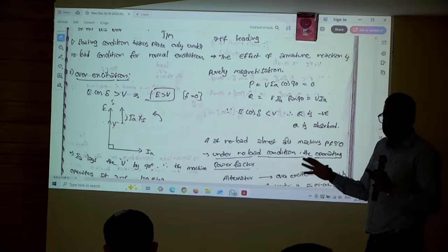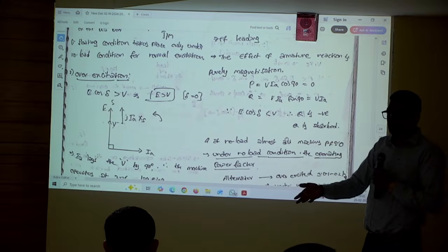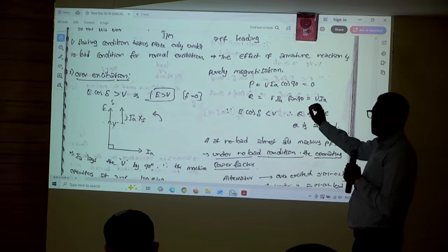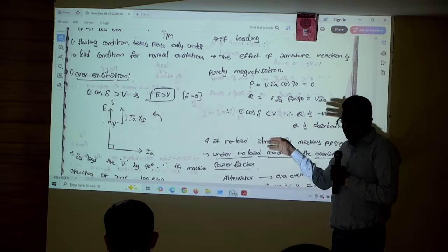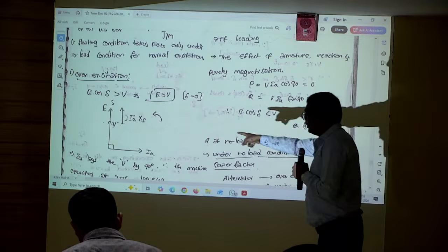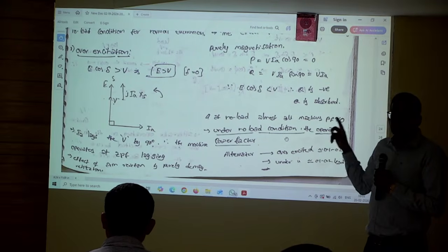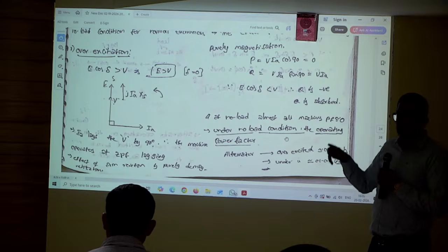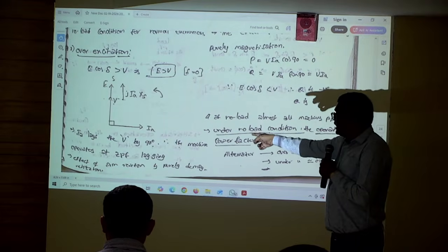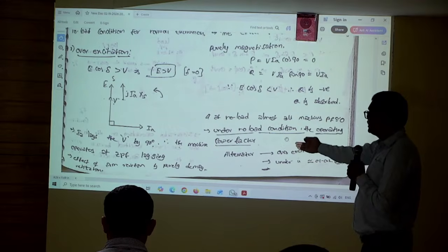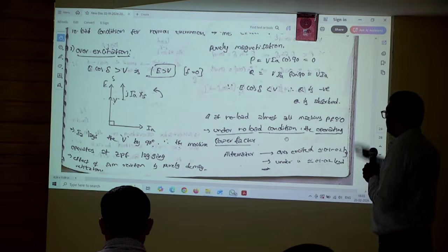Before that, we need to establish the system first. Supply should be available stably. For that, this is the analysis at the generator level. So always I am mentioning load angle is now assumed 0. When E cos delta is greater than V under over exciting condition, see the phasor diagram, current drawn, over excitation, ZPF lagging, armature current lags behind the voltage. Yes, the resultant IA lags V by 90 degrees, machine operates at ZPF lagging. Now, effect of armature reaction is demagnetizing, correct.